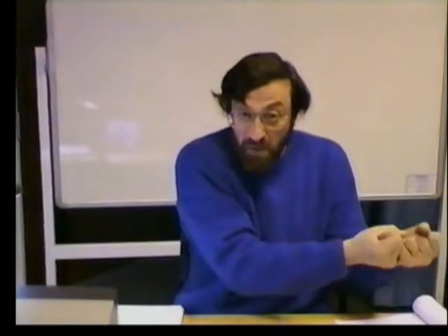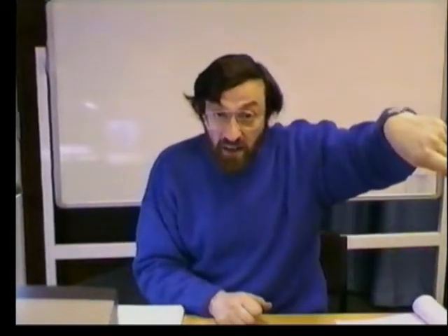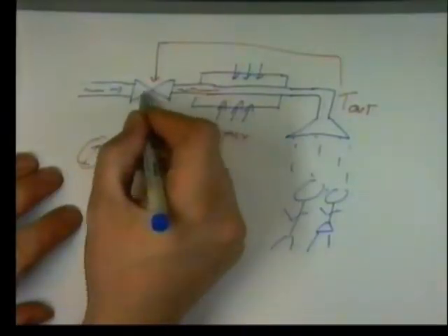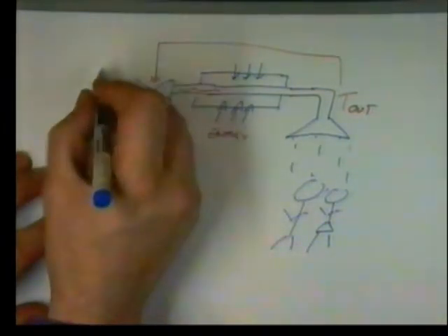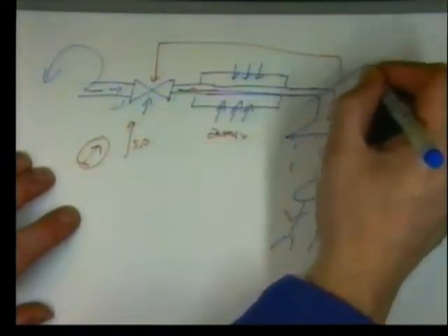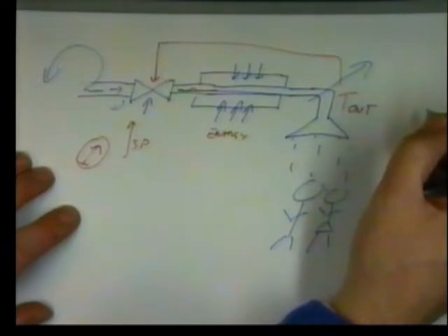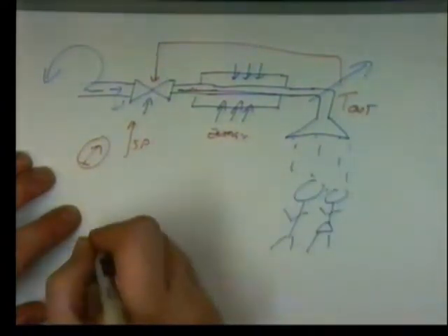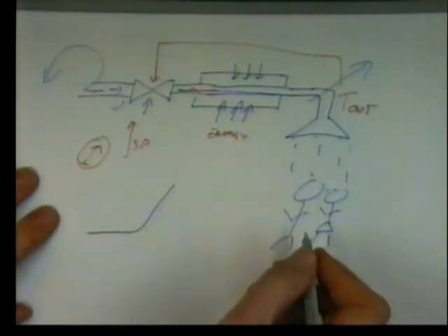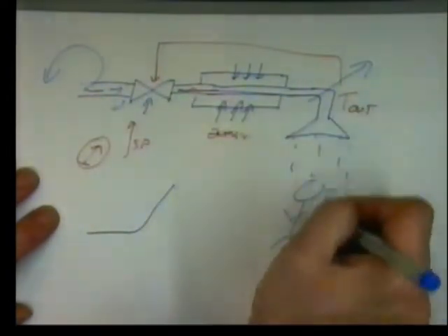We have a shower in the shower room, taking water from a water pipe, which is also feeding the flush toilet, and that is a lot of water. If that pressure of water is suddenly removed from the system, the amount of water that flows through this pipe suddenly drops off rapidly because the water is being diverted elsewhere. So that small trickle suddenly shoots up in temperature rapidly. If we looked at the temperature profile, suddenly there's a vast increase in temperature due to the sudden drop in water pressure into the shower.